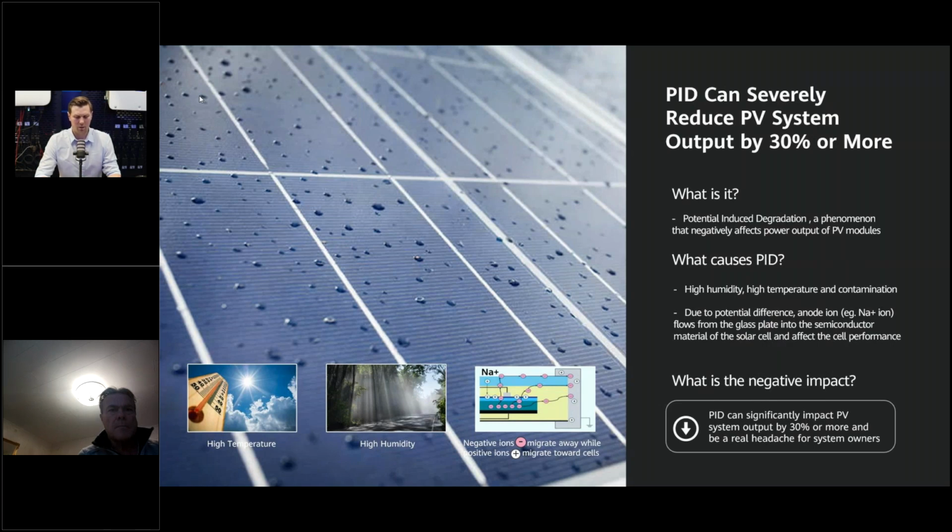So we have the positive and negative pole of our PV generator, and we have the grounded frame, whose potential is about 0. This potential causes the following thing: on the last and first PV module, some ions go through the glass to the semiconductor structure. It contaminates it and decreases the performance of the PV modules.